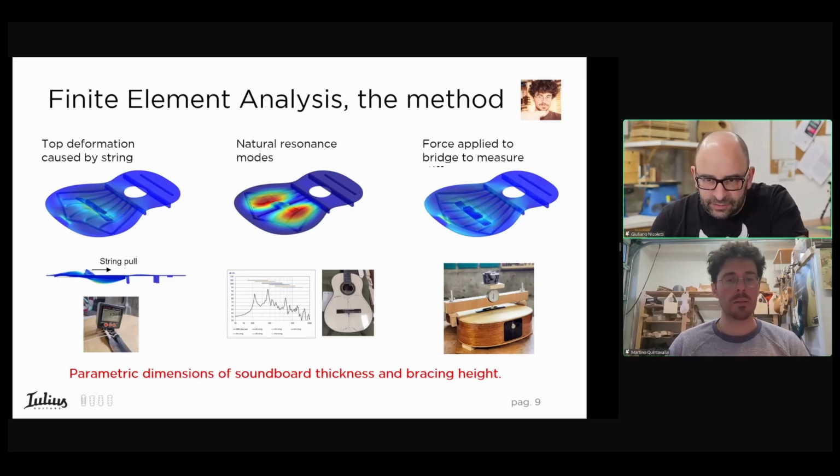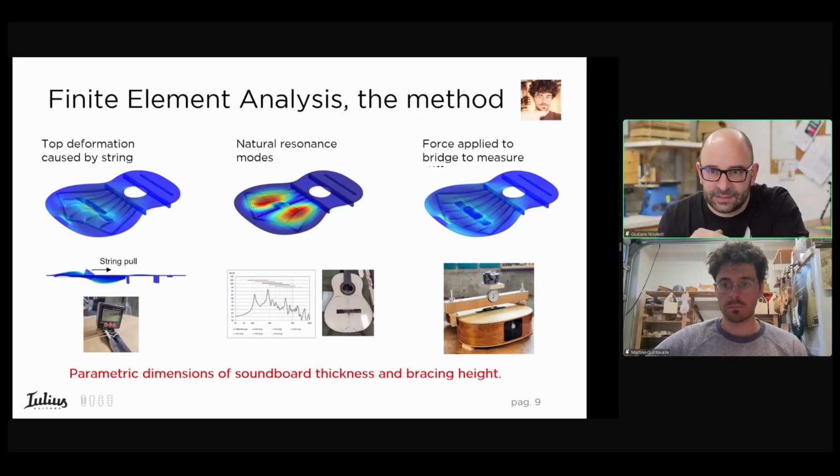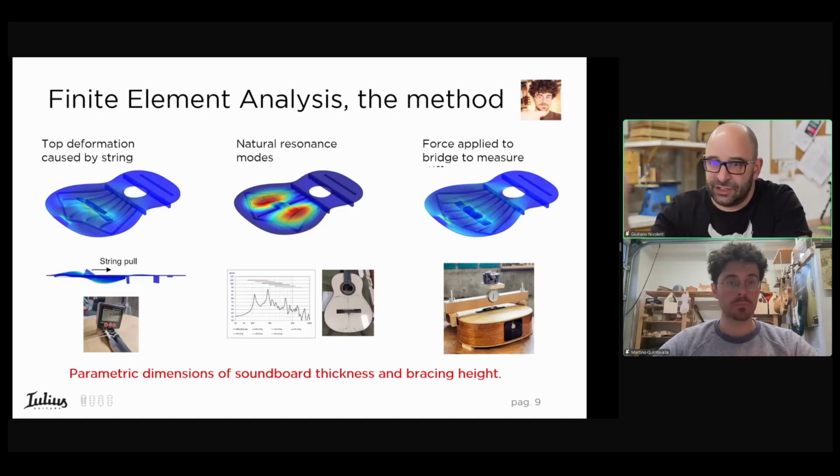And keep in mind also that different bridge geometries and materials affect the frequency differently, because of course the bridge at the same time adds stiffness and mass, and if you think these two changes could balance themselves. Eventually, it is the higher mass that really drops the resonance frequency of the monopole from before and after, but also its rigidity is pushing it higher. So especially the cross mode, as the cross dipole and the cross tripole frequencies are shifted much higher.